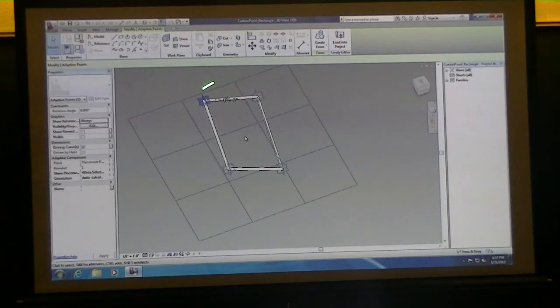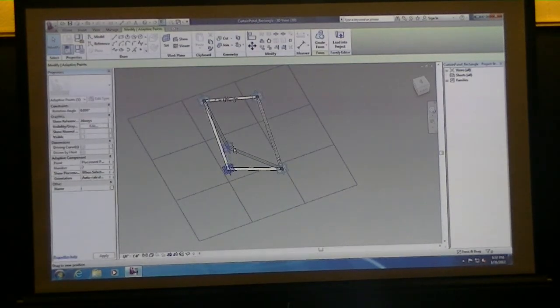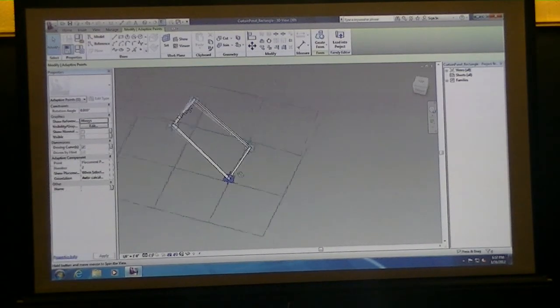So when we made this pipe, you wanted to really make sure that you snap to the center point of that actual point that was on the reference line. And that's going to be very important on everything that we do here. We have to really make sure we're snapping to all the points, because if you don't, then when it gets applied to another surface, it doesn't know what it should be referencing, and that's when you'll get the errors. And it'll want you to basically delete your component from the surface. So that's a good test for you to move that up and down and see what kind of results you get.